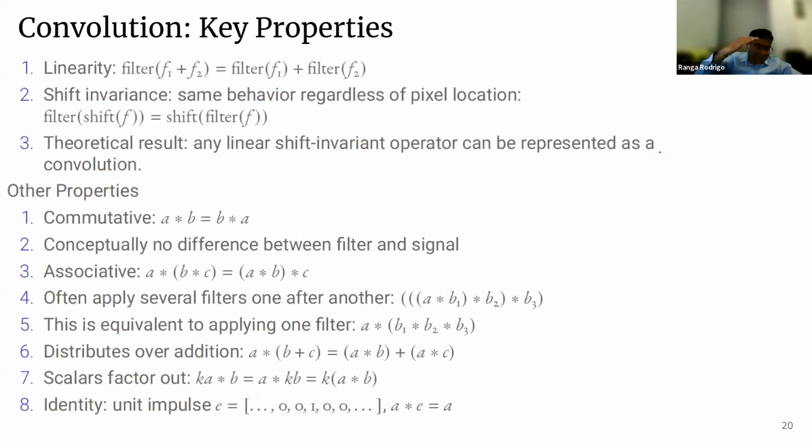Okay. So the properties of convolution that you may have studied in your signals and systems apply. That means if you filter two images, it is equivalent to filtering them separately and adding. And shifting operation is possible. Commutative, it is like 4 times 5 is equal to 5 times 4, right? That is called the commutative property. So this property is applicable to the convolution also. Therefore, it does not matter what you consider the kernel, what you consider the image, it can flip.